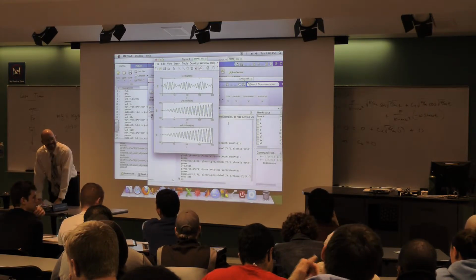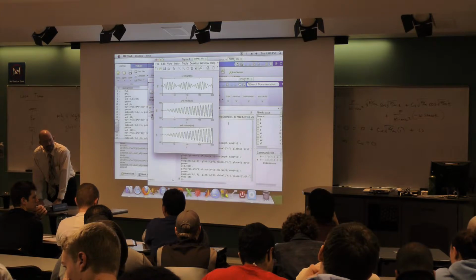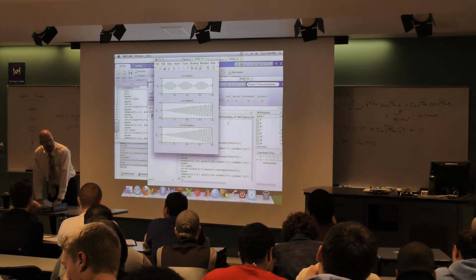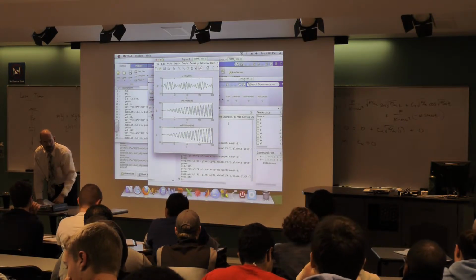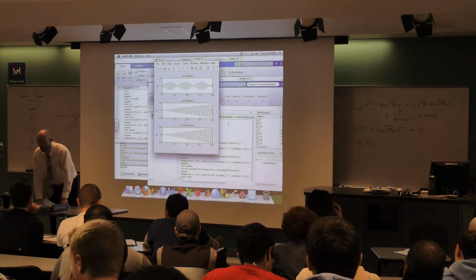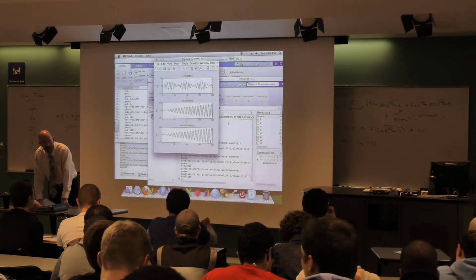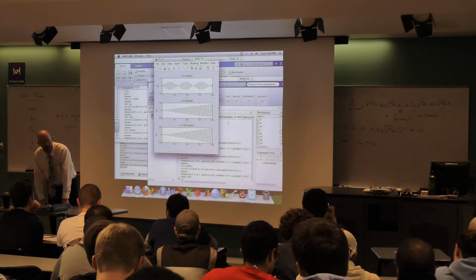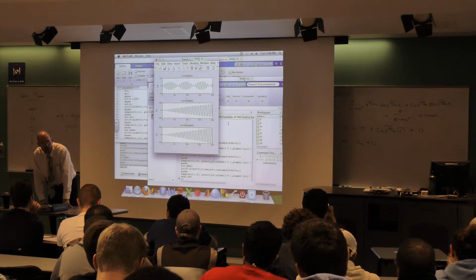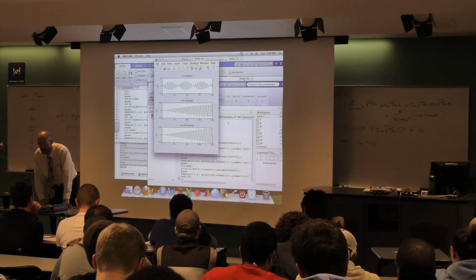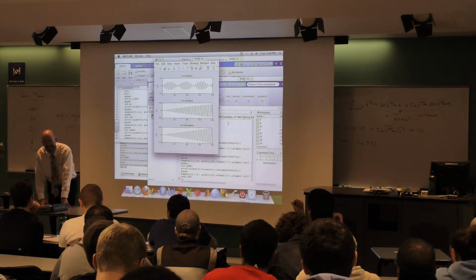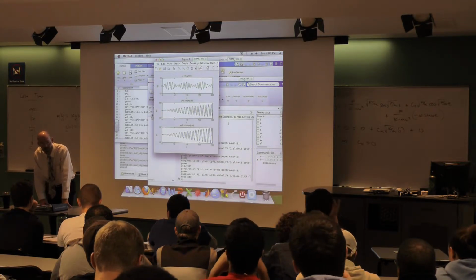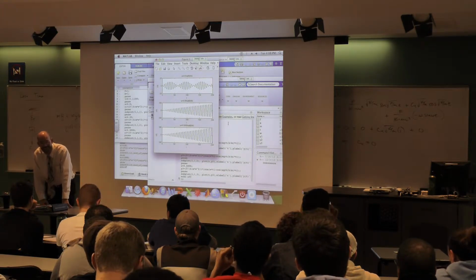Yes? So how did people that build bridges prevent that from happening? Yeah, that's a great question, because really modern day analysis understands this stuff pretty well. Closed form solutions for things like springs and masses and the kind of stuff we're doing here have been around a long time. So they would have known that, and in fact, I believe in the case I cited, the Tacoma Narrows Bridge, they did do structural vibration analysis in the design, but they didn't consider all the modes